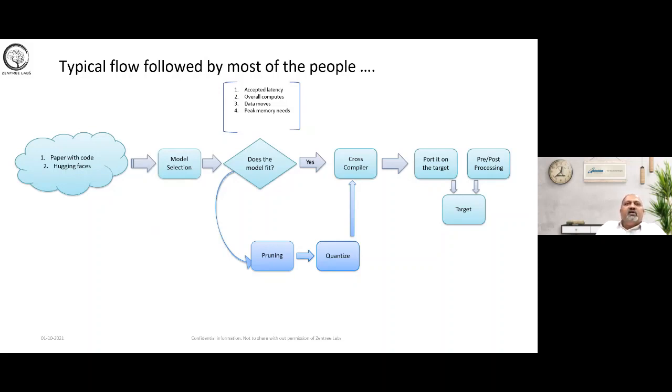One is the accuracy of the model, and the second thing is acceptable latency. Can this model process my data in the expected time, which can be anticipated through the GFlops required by the model, that is, the floating point operations needed per second? The GFlops itself will also give how much compute you need. And data movement is another big challenge in neural networks; it's not just compute. Many people are coming up with domain-specific hardware accelerators for deep learning neural networks. We have been seeing them.